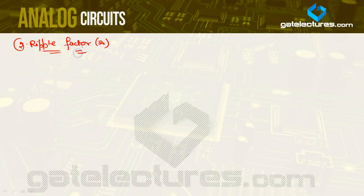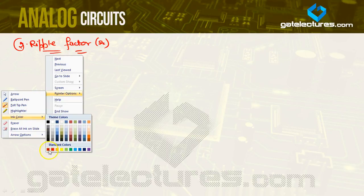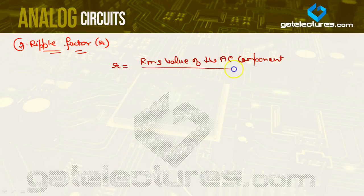You know, the definition of a ripple factor is basically the ratio of the RMS value of the pure AC component to the DC component. We know that the ripple factor is defined as RMS value of the AC component upon DC component.